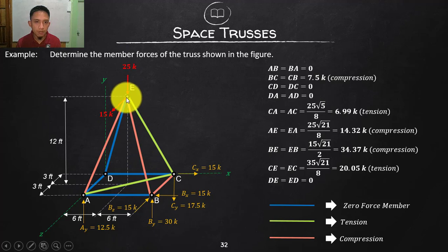At the same time, because of this Z force pulling that one, all the load of 25 is now concentrated on these 2 front inclined legs. So these are now being relieved of the effect of 25 within these 2, and actually this will not be stressed. Why? It is not supported. Even if there is a result of 25 on this member, it is not resisted, so it is free to move. It means it is not stressed.